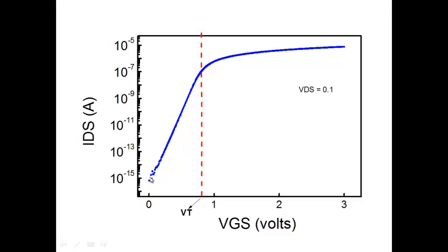Subthreshold leakage here, the off-state current here. Don't get confused by this value here. This is 10 power minus 15, for a 5 micron transistor, and for the width of the transistor I've taken 1 micron, right? Suppose I have 50 micron. So the current would become 50 femtoamperes. Fine, it's very small, but then that's 5 micron, right?